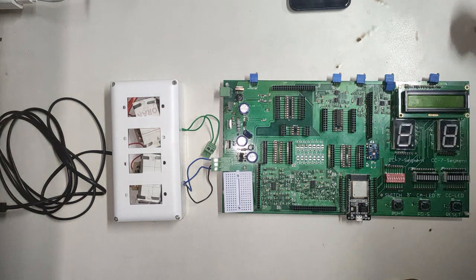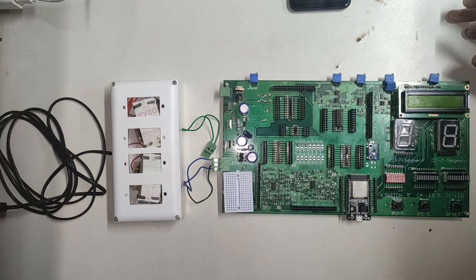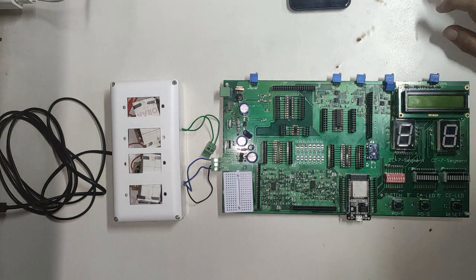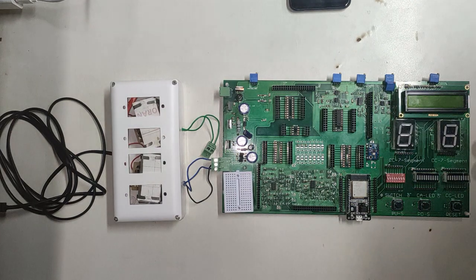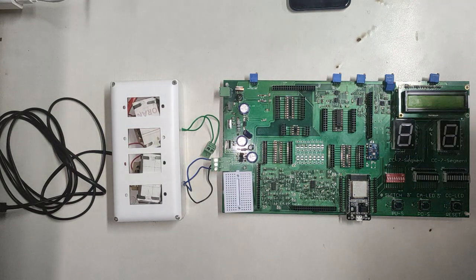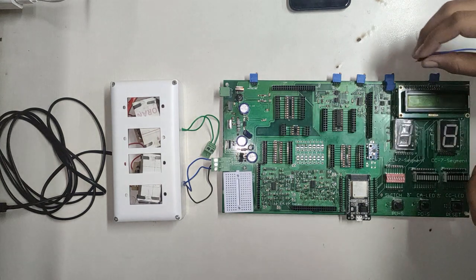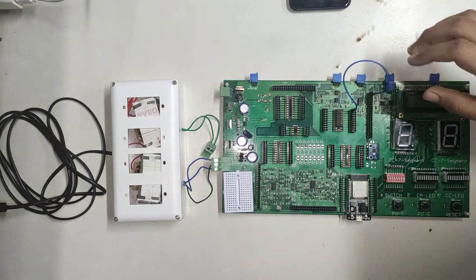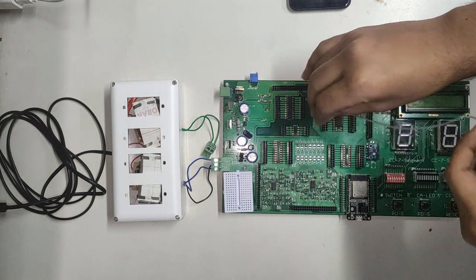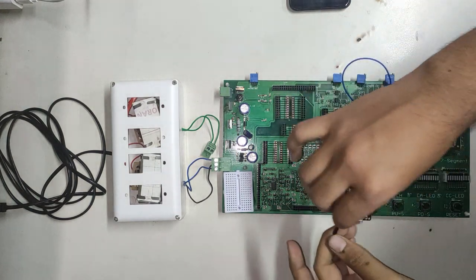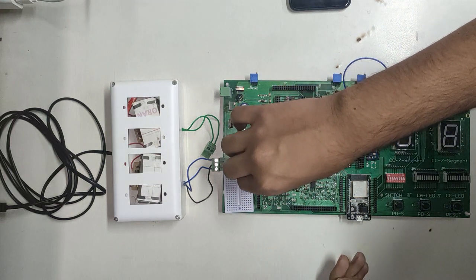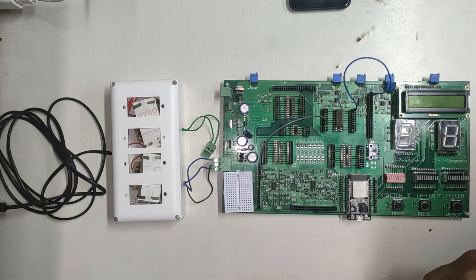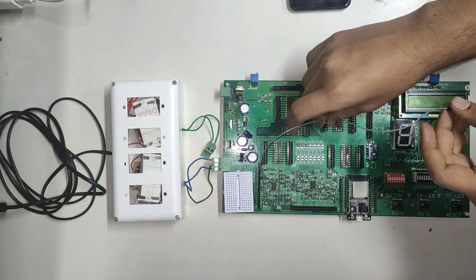To make the connections for the 4-bit comparator, you must go through the pin diagram of IC7485 carefully, because the pin diagram is not similar to that of earlier ones. Pin number 16 is connected to VCC, and pin number 8 goes to the ground. The 3 pins above the ground are our output pins.